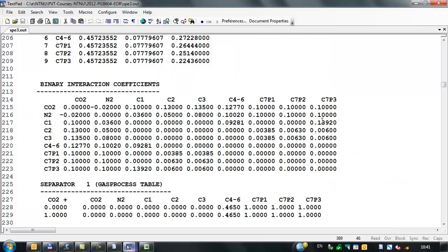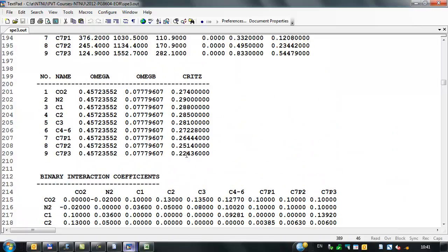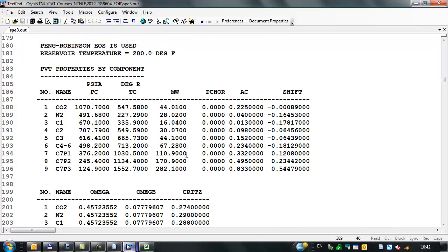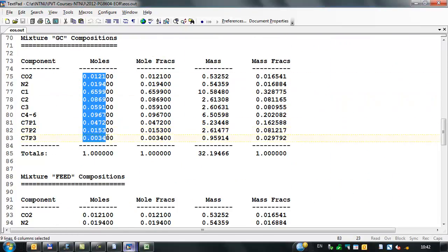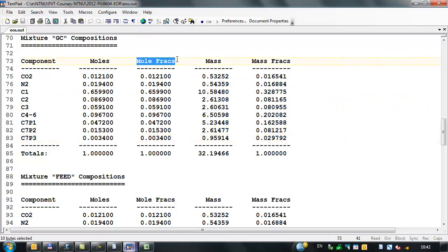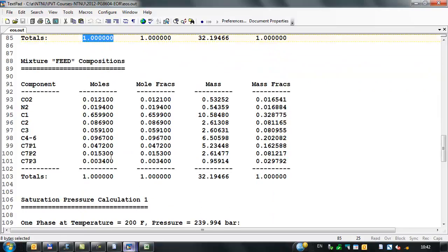And if I don't see anything there, we've got the compositions. Those sum to 1 because you read in moles, then it calculates mole fractions internally. So we didn't type an extra 0 or something in there. It does sum to 1, so that's a good sign.